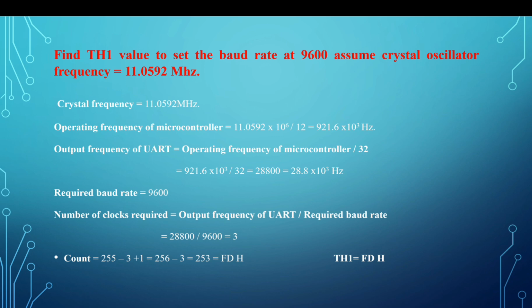So it creates some error in the serial communication. Baud rate should be matched. The number of bits transferred between transmitter and receiver should match. So rounded values are required. That is why such an odd value is used. This odd value will always give you a rounded value for your IBM PC selected baud rate.